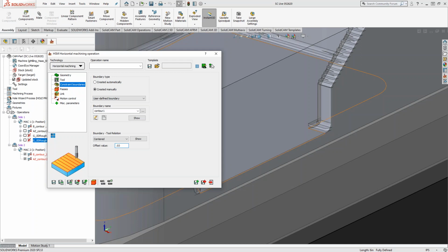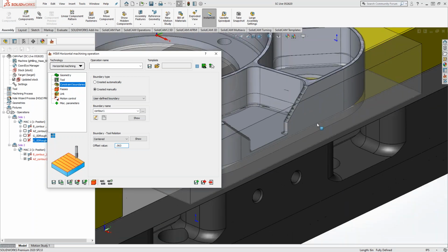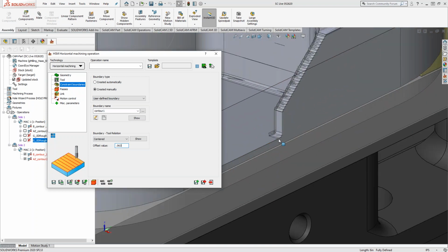So if I say maybe offset it by an additional 30 thou, or actually let's offset it by the corner radius, it actually goes just that little bit out. That's not going to let it go too far out where it's going to do things I don't want it to do, but it gives it enough room that it can wander outside if I need it to.